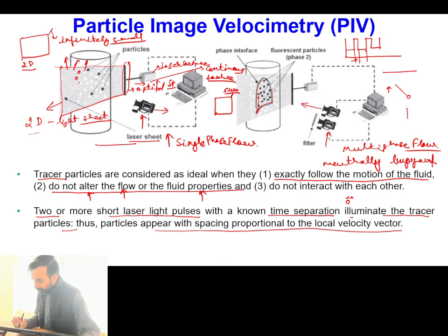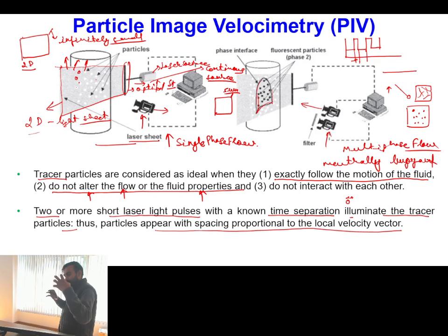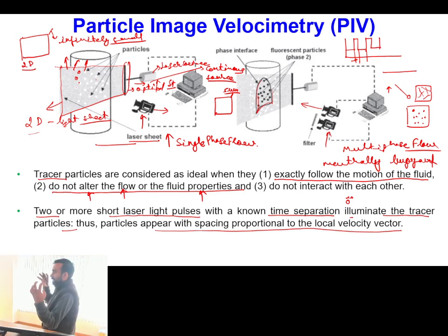And in your photograph, instead of single particle locations of bright intensity, you will find the photograph having some dull random streaks. Okay, so that's why whenever the camera is capturing the photograph, corresponding to that instant only, we just illuminate the fluorescent particles. Is this one clear?